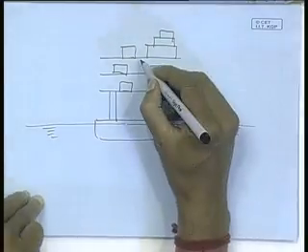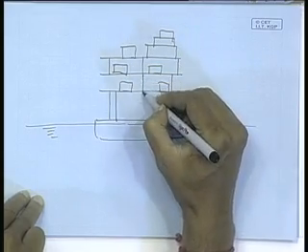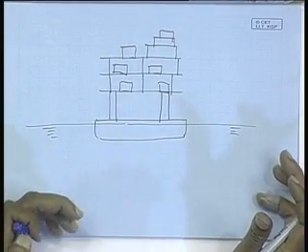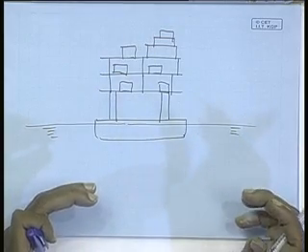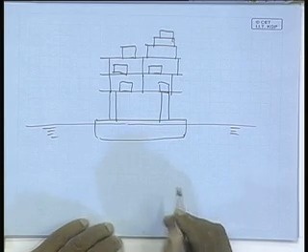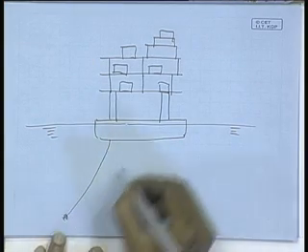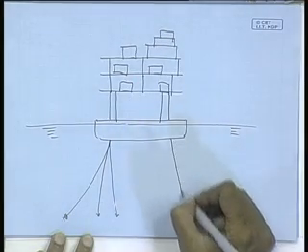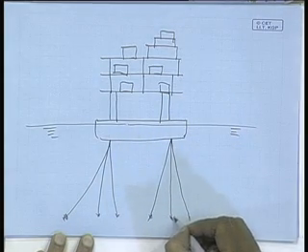Now, if it remains just like this, then obviously it will keep on drifting in the sea, which you cannot have. You will have to have one particular location where it is located, right. That is what is done by the tension legs. It has a mechanism of connecting to the seabed. Suppose I am schematically drawing 3 tension legs.